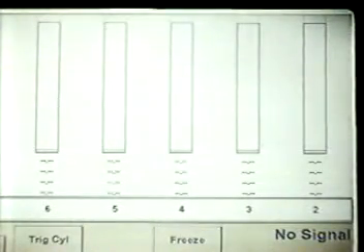Okay, what we're going to do here is a cranking kV test on this DIS 3800 system, and we want to prove to you that the kV bar graph and the kV demand is directly proportional to compression. After you see this good reading on the scope, we will create a compression problem, and we will show you that a cranking kV test will in fact pinpoint the exact cylinder with the compression problem.